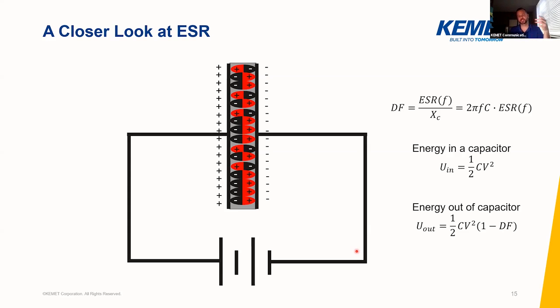If you take an equivalently sized capacitor and increase its voltage rating, you'll lose its same capability of capacitance. Think of it from an energy standpoint: you're building up quite a lot of energy in that charge separation between the electrode plates, and at some point that electric field will be large enough that you can actually cause dielectric breakdown, especially if you get the plates really, really close together. So that's the relationship between capacitance and voltage.